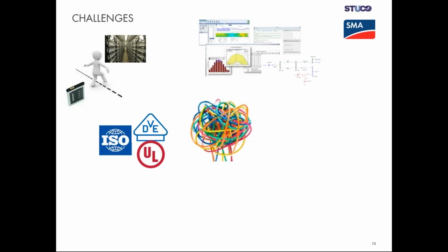I want to give you one piece of information. Fred mentioned it already. It's the ISO 8528-5. And this is an ISO norm for the grid quality of generator systems. We just took it as a reference because we did not know what we should compare to. There is no norm for a grid-forming inverter, let's say. So we more or less gave ourselves the threshold and boundary limitations of this norm and made sure we meet at least the given standards, and we are not only fulfilling but exceeding them.